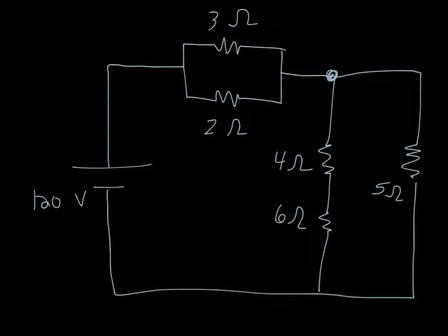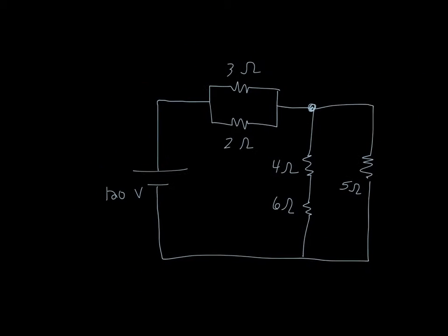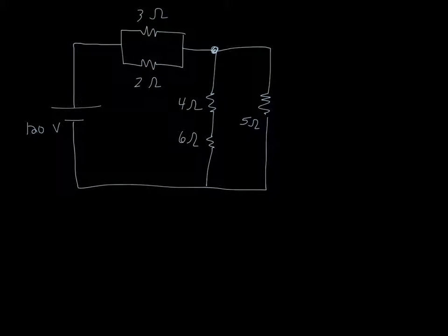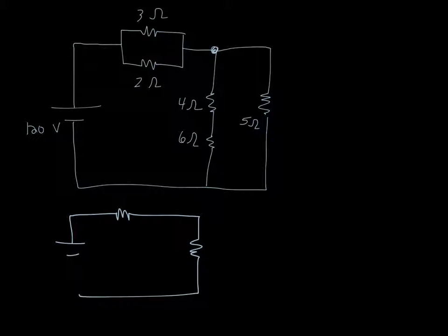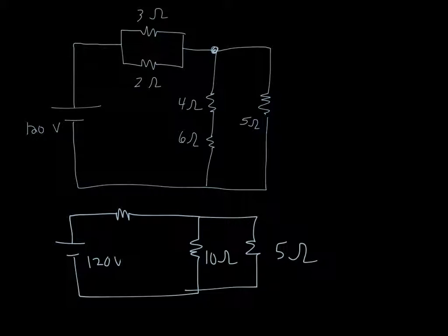So I'm going to redraw this diagram. Remember, this is how you have to do it. Redraw the diagram every time. Up here, I need one resistor. Here, I need one resistor. And here, I already have one resistor. This one is known. That's 5 ohms. How about this one right here? What should it be, everybody? Why do you know that? It's in series. So put a 10 here right away. That one's done. The one on the top is the tougher one because it's in parallel.